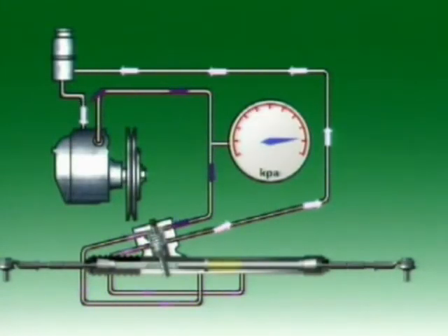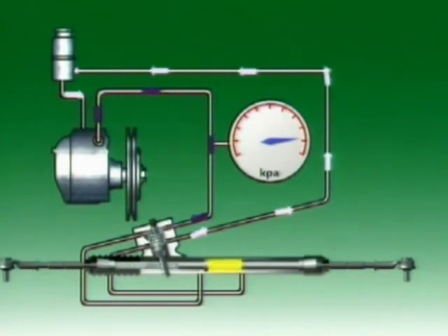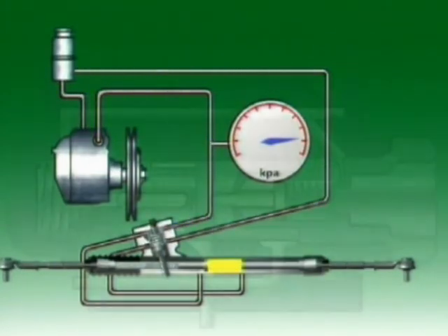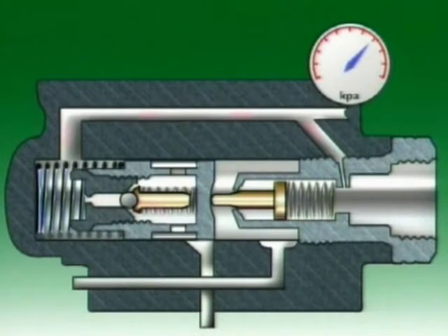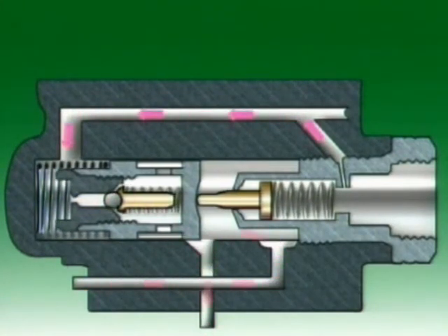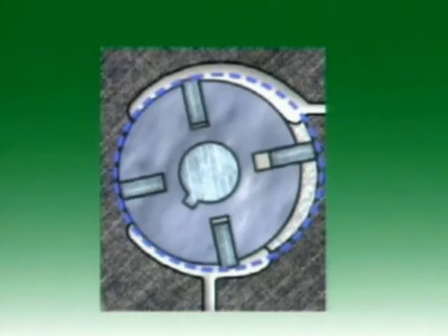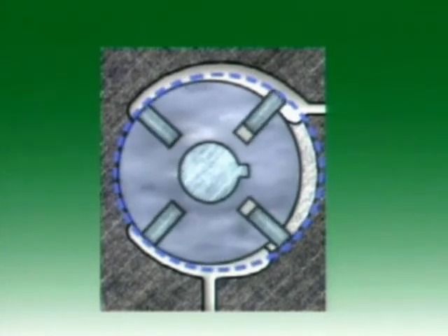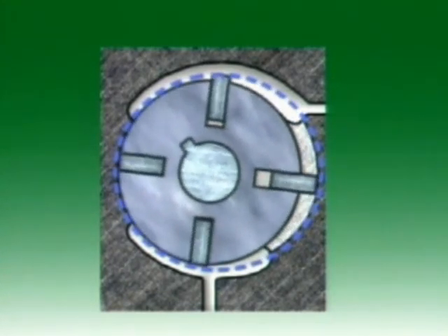With the steering wheel held at full lock, the steering rack power piston chamber becomes fully pressurized and fluid flow stops. This high pressure is transmitted back to the spring end of the control valve, opening the pressure relief valve. A small amount of fluid passes through the pressure relief orifice, providing a pressure drop. The valve moves and uncovers the return port to the pump inlet. A predetermined relief pressure is thus maintained. The pump is normally a vane type, with sufficient capacity for all operating conditions.